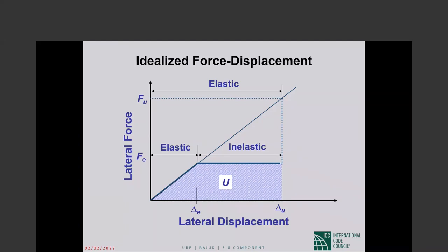If, on the other hand, we are content to design for a relatively high design force level, then we will not need all that terribly much inelastic deformation capacity. Then our detailing may be, relatively speaking, crude, not that fancy. Okay, so these are the very basics.